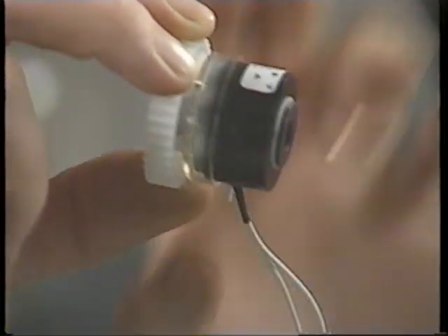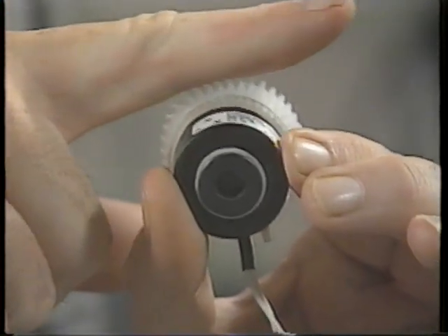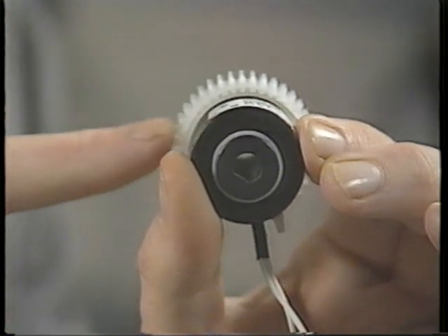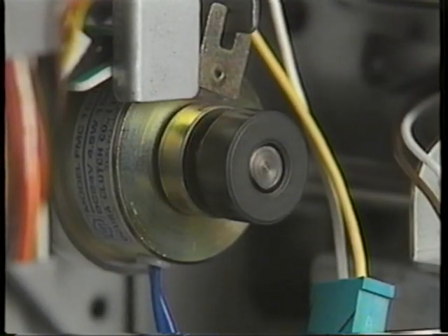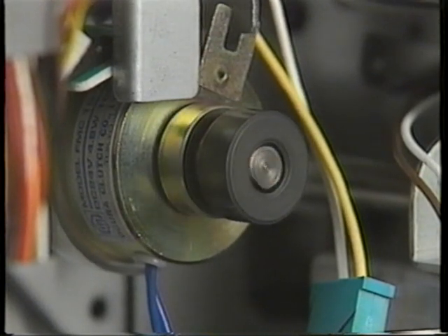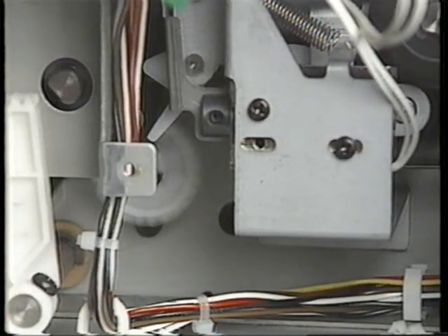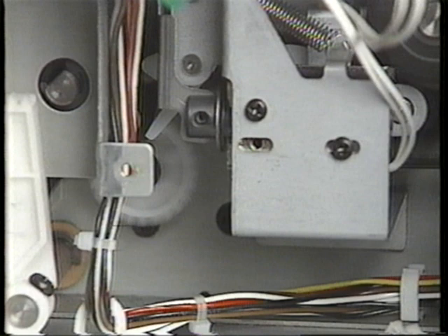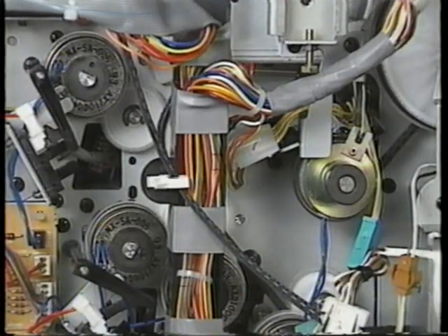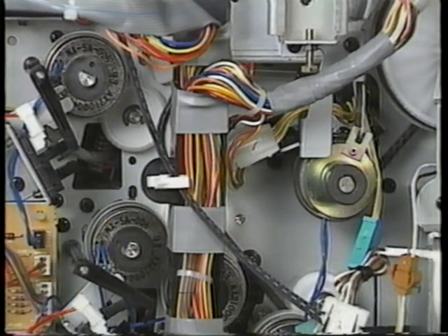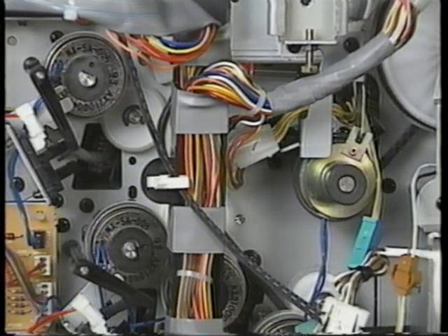Now turning like a solid piece, the clutch transmits drive through the center shaft and onto whatever component needs turning. By activating and releasing magnetic clutches and solenoids, the copier's control system can start and stop the paper feed rollers very precisely.